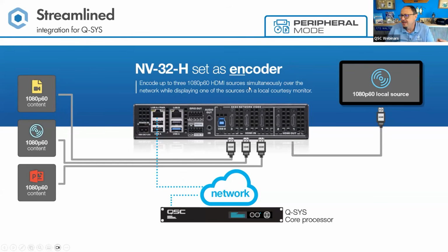This is 1080p. In 1080p, you can plug in 3 independent 1080p sources, and you will be able to stream all 3 of those out of the network. This all really goes down to the bandwidth of the network ports. These are 1 gig network ports. Our compression algorithm makes us send our 1080p out at about 250 megabits of bandwidth. If you take 3 of those, that's 750. That leaves a little headroom for audio processing and whatnot.